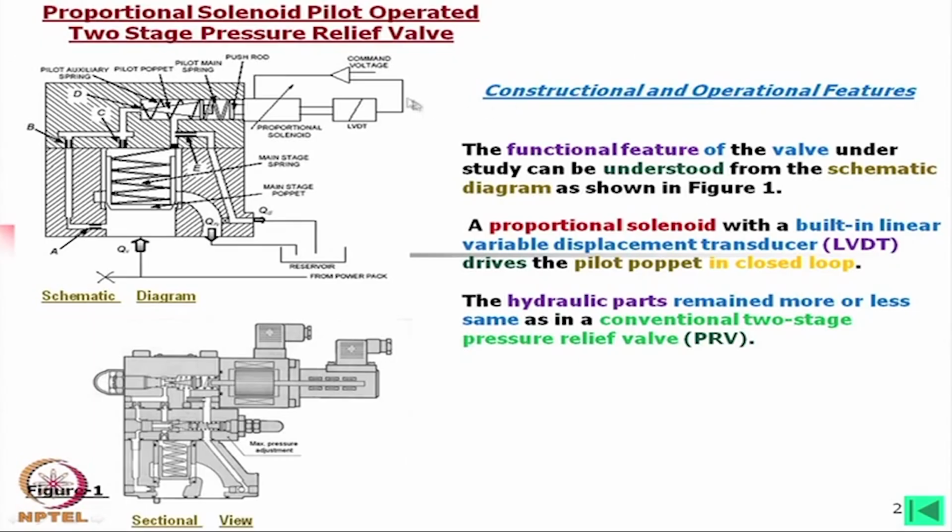Whereas, in this case it can be made closed loop through the main drive. There is a card, of course, and then it might be a microprocessor, it might be manual, it might be a computer, but there we can set a program so that it can correct all those errors. Of course, it should be within a limit. So, therefore, these valves are less expensive in comparison to the servo valves, but we should look into the purpose.